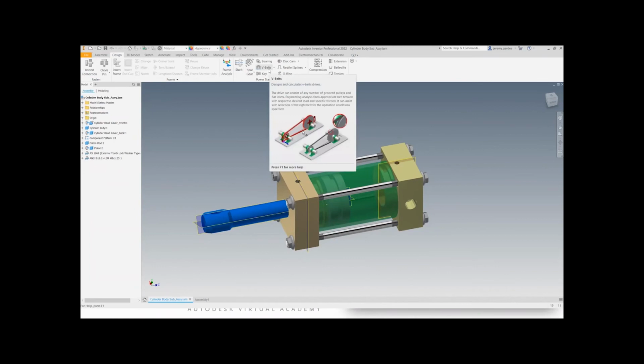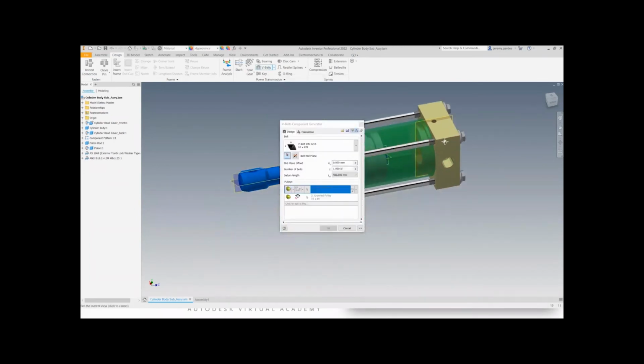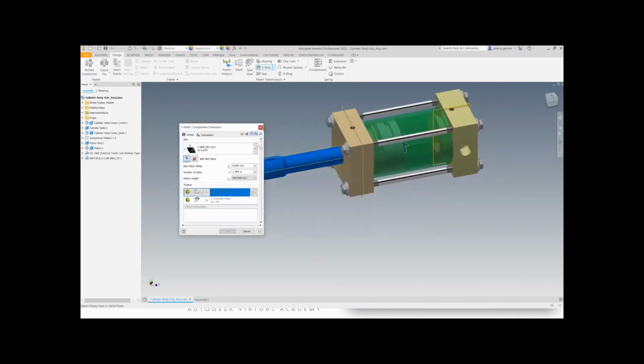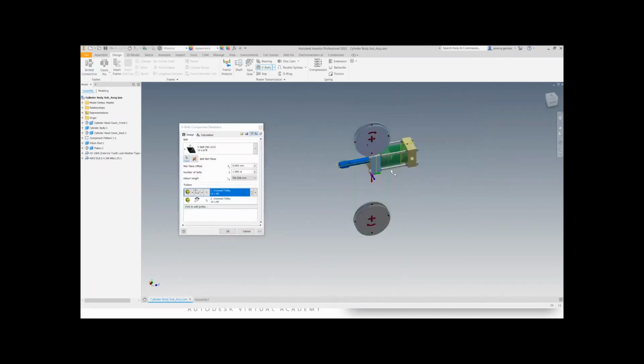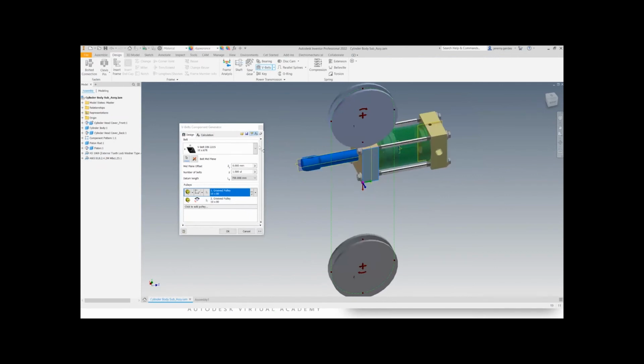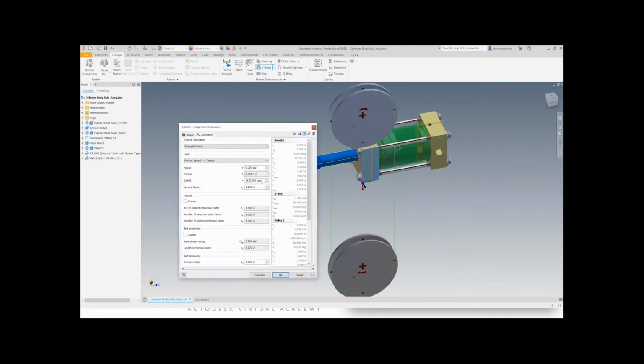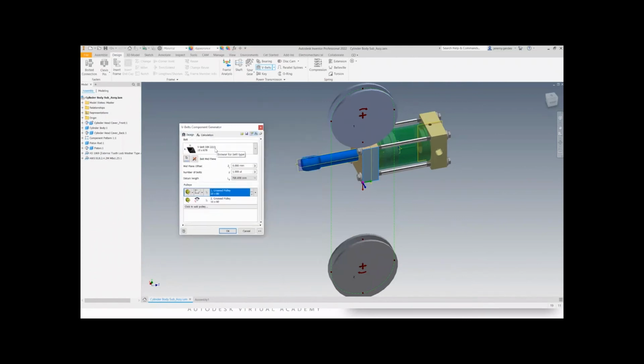One thing I've used for quite a while is the V-belts. So you can, we'll just say real quick, select that plane, and it automatically puts in pulleys, and I can adjust the size of the pulleys, the RPMs, calculations like that. And then I can check for strength to say, okay, at 14 horsepower, it's spinning at 340. It'll tell me that this size of belt is not going to be adequate to the standards that I need.